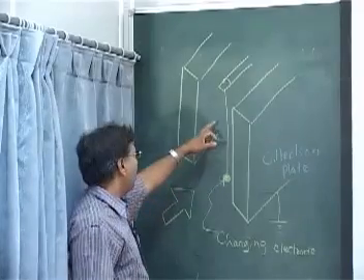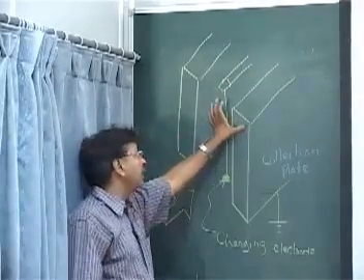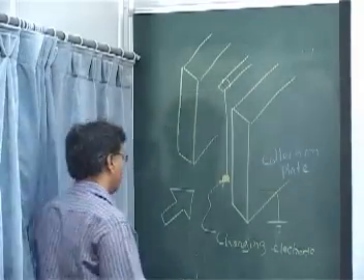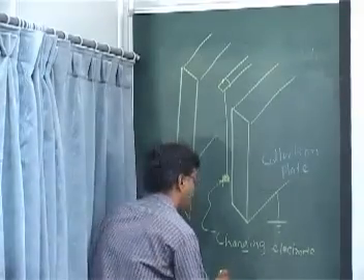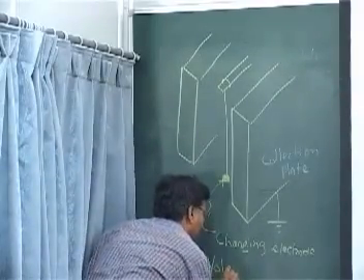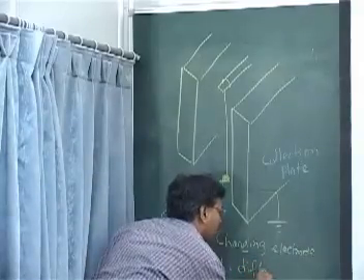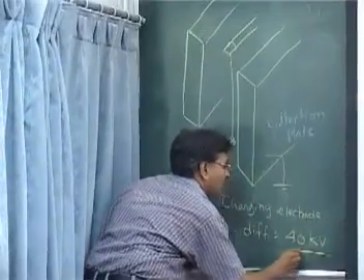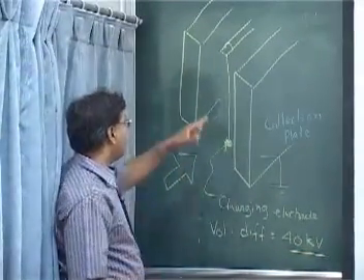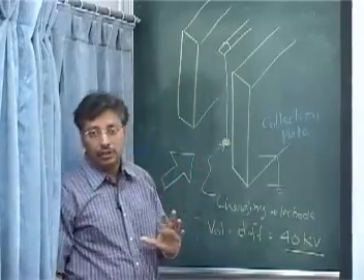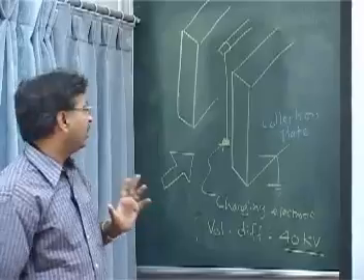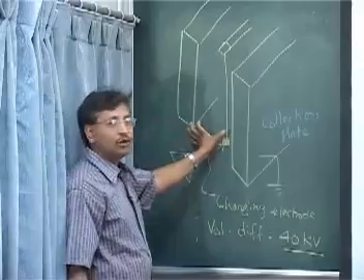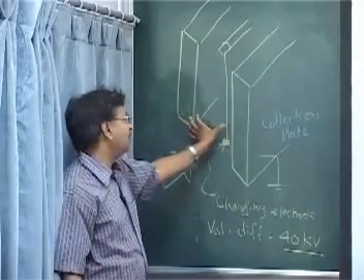The voltage difference between the plate and this electrode is about 40,000 volts, 40 kV, and the electrode is generally negatively charged. It could be positively charged also, but generally it is negative. The distance we are talking about is about 3 to 4 inches between these two plates.